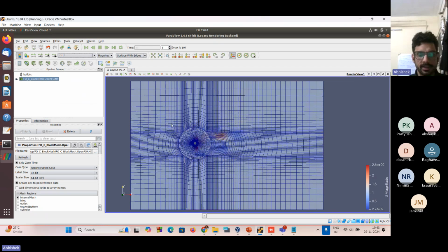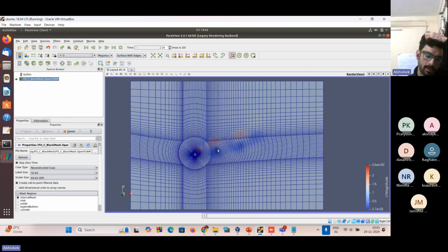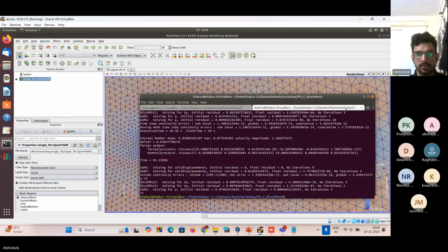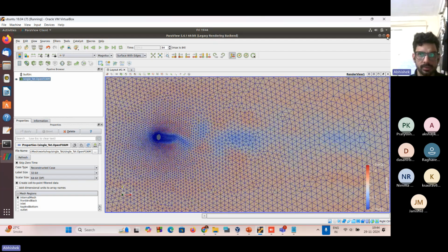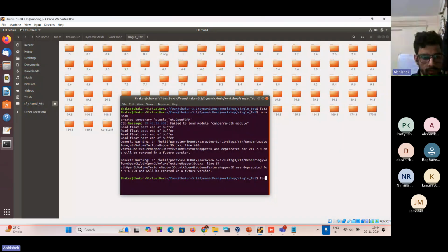So this is a very good mesh if you have a single rigid structure for which you can make a hex mesh. You see, it can handle very large deformation. But I don't think that this can handle such large deformation. So what we will do is go from plane to.